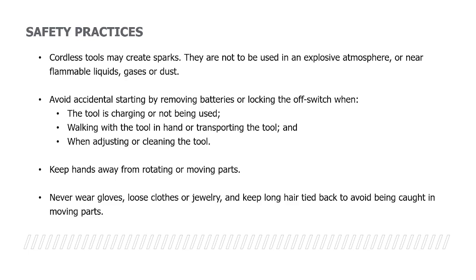One of the things you want to keep in mind with gloves, particularly if you're working in a very tight area, is that if for some reason a router bit comes in contact with your hand that you have gloves on, or maybe the gloves you have on do not fit you correctly or are too large for you, that tool could pull that glove directly in, and it could potentially pull your fingers directly into the tool itself. So use a little common sense out there when you use any type of power tools.